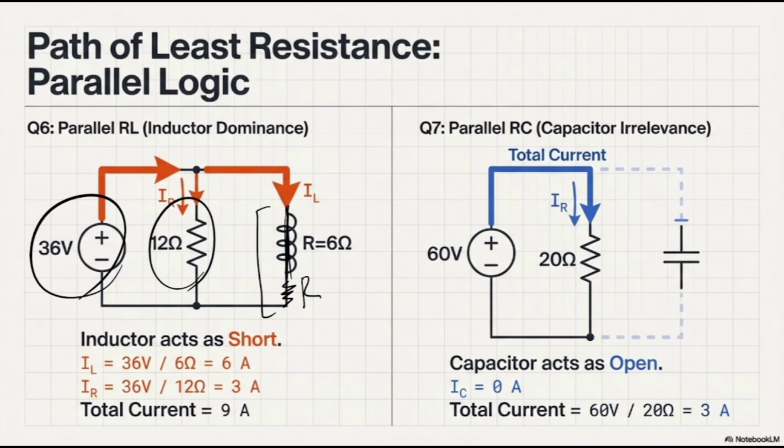So you have R is 6 ohm, R is 12 ohm, and you do have 36 volts. So simply you can find the amount of current that goes this way, and so finding the current in the second branch means that you can find the saturated current for your inductor, right? So the saturated current would be what? It is going to be 6 amp.